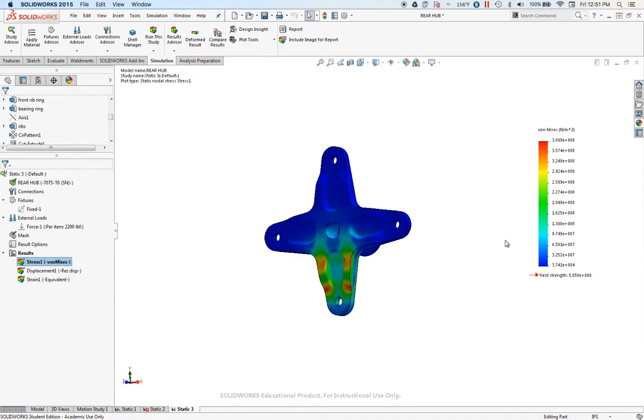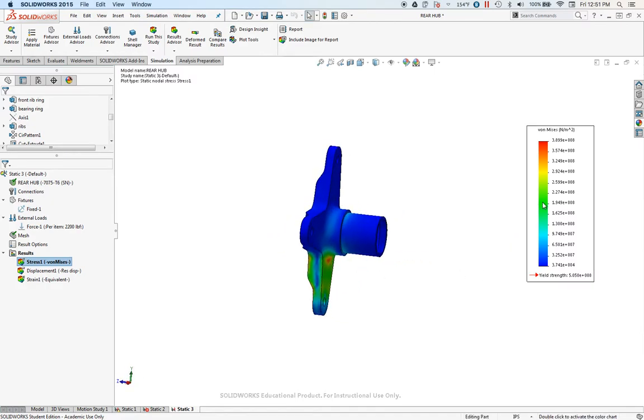It means the algorithm is unable to predict basically what's going on. The algorithm is only good in the linear elastic region of the material. So when you see that it yielded, that means it kept going and trying to calculate past the elastic region. And if you know the stress strain curve, the properties don't stay the same. So your results mean nothing if it yielded.